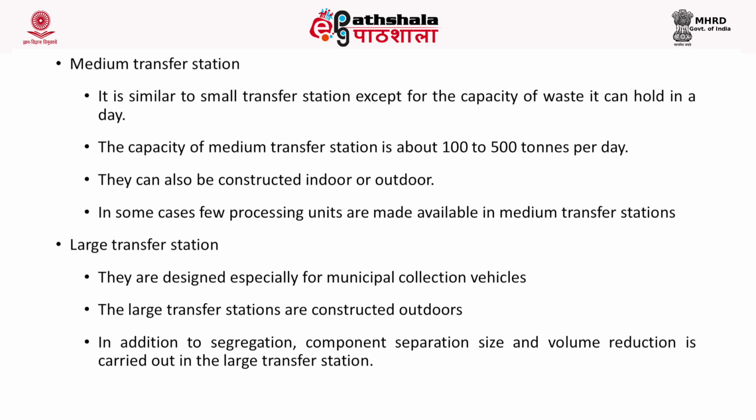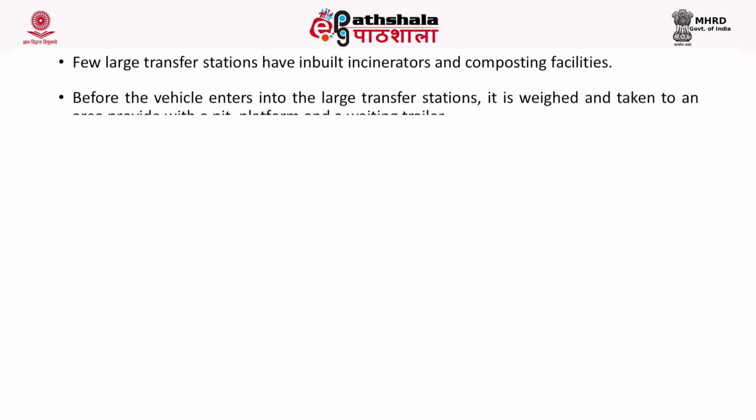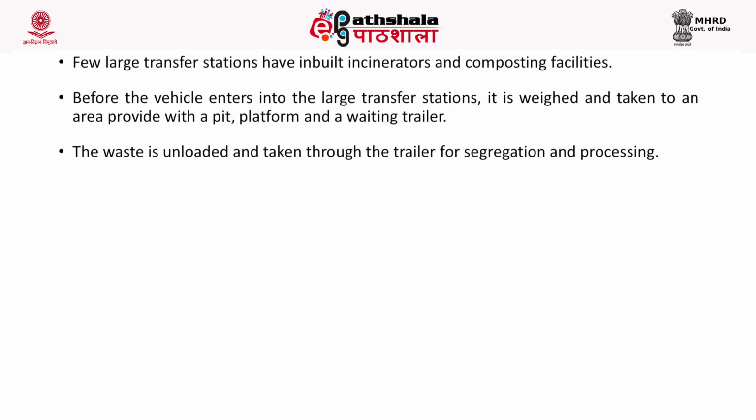Now, large transfer stations are designated especially for the municipal solid waste collection vehicles. These transfer stations are generally constructed outdoors. In addition to segregation, you have component separation, size and volume reduction facilities available in a large transfer station. In some large transfer stations, you will also have inbuilt incinerators and composting facilities.